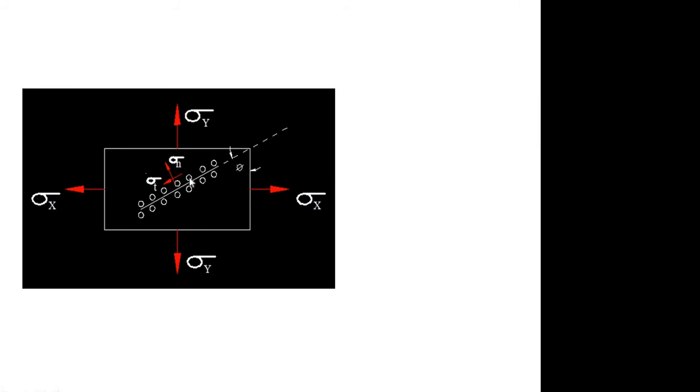So what happens, even if you are applying a stress which is much lower than 100 units of stress which the material is capable of bearing, there is a possibility of developing a normal stress in some direction which is more than the bearing capacity of the material. As a result, the material will fail in tension along this plane. That is, it may develop a fracture in this direction due to tensile loading. So this is one case.